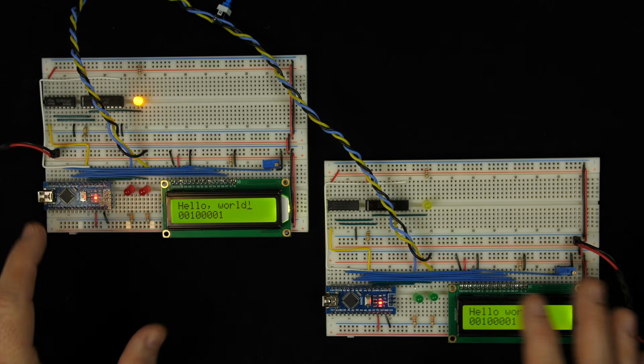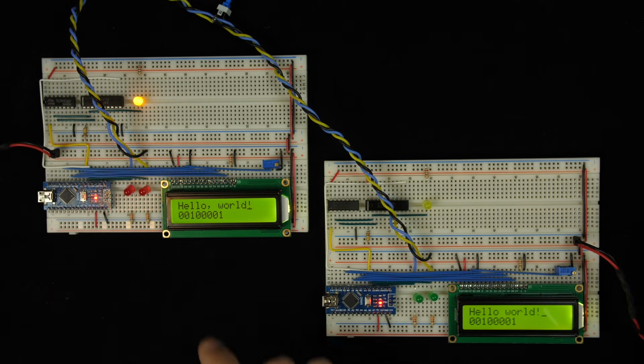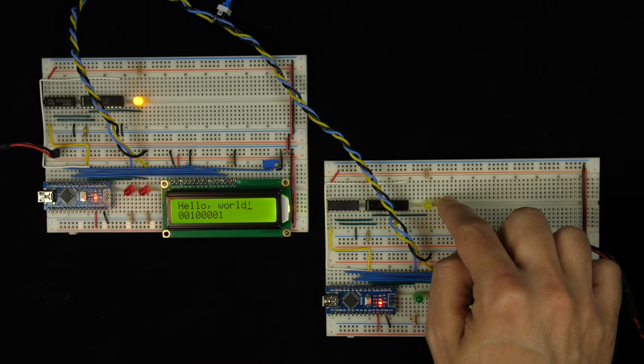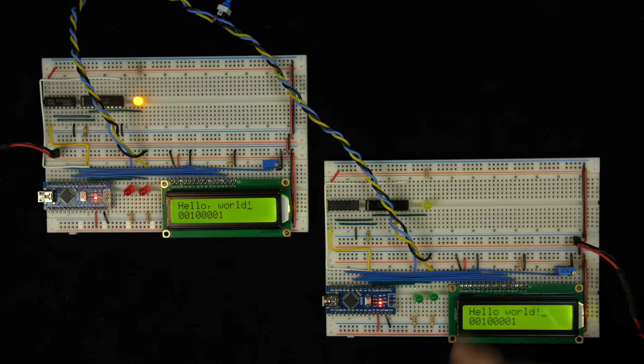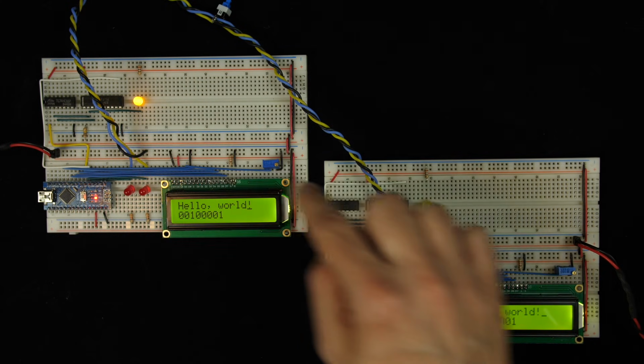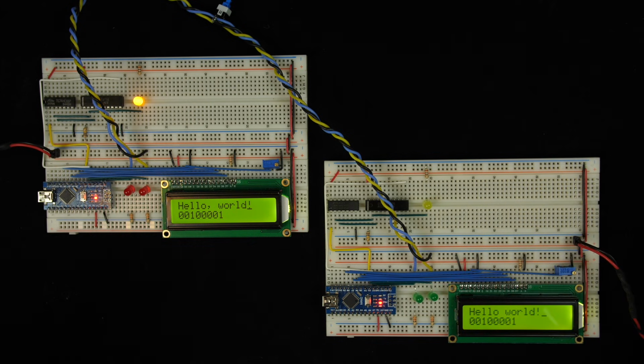So the only way this is going to be useful is if the transmitter is able to send its parity bit to the receiver somehow, so the receiver can compare it with its own computation. So how do we get the value of this parity bit sent over to the receiver? Well, I think the easiest way is to have the Arduino just read the value of the parity bit and send it the same way it sends the rest of the message.